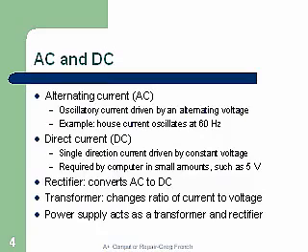Rectifiers convert AC to DC and chop the voltage, so we only see a positive-going or a negative-going voltage, not positive to negative. Transformers change the ratio of current to voltage. We can use a step-up transformer to increase the voltage, or a step-down transformer to reduce the voltage. We'll talk more about that.